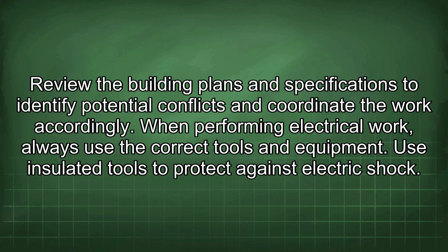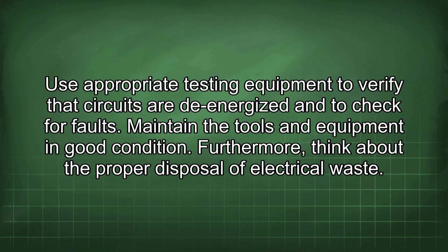When performing electrical work, always use the correct tools and equipment. Use insulated tools to protect against electric shock. Use appropriate testing equipment to verify that circuits are de-energized and to check for faults. Maintain the tools and equipment in good condition.